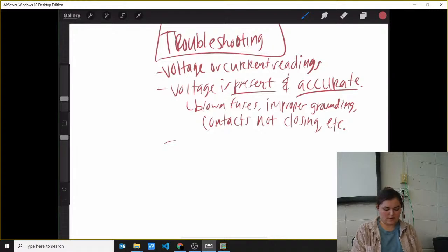And the last paragraph is, motor drive manufacturers provide software programs to calculate the cost savings realized when using motor drives with pumps and fans. Given info such as motor horsepower, motor efficiency, and cost of electricity, the program calculates the annual cost savings and the payback period. In many cases, the software is available free or as a download from the website. So that kind of answers your question from earlier. It's going to come with software already.